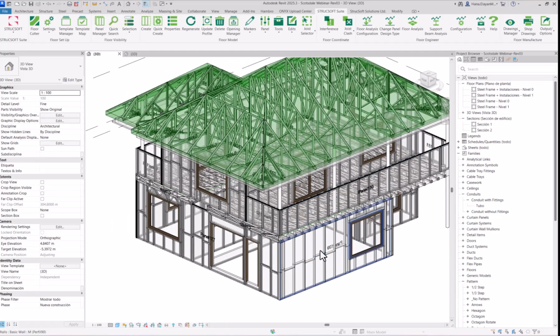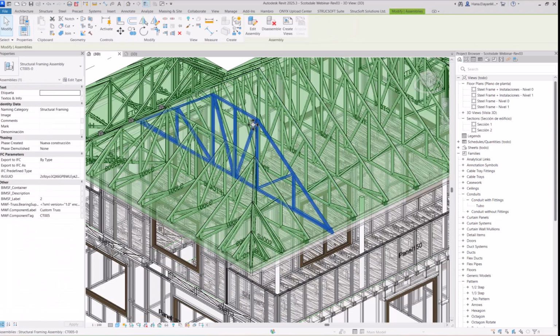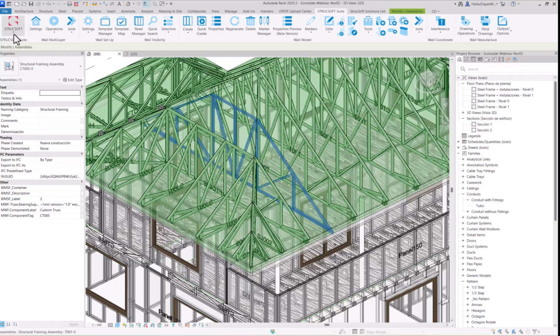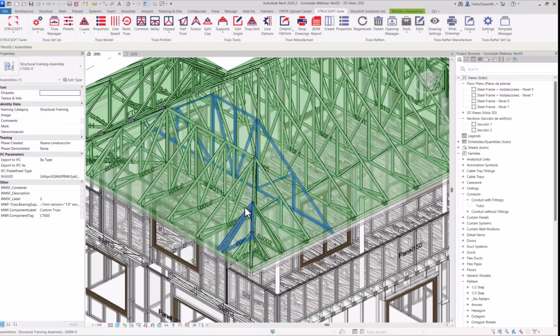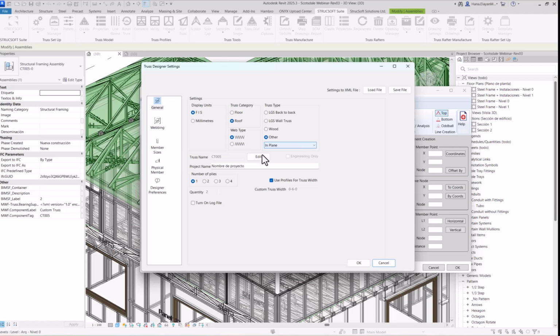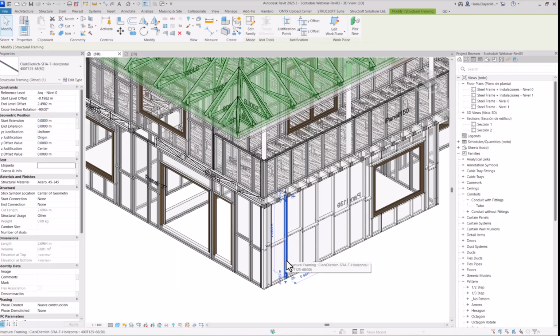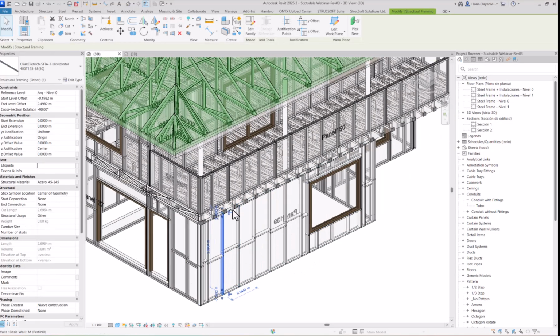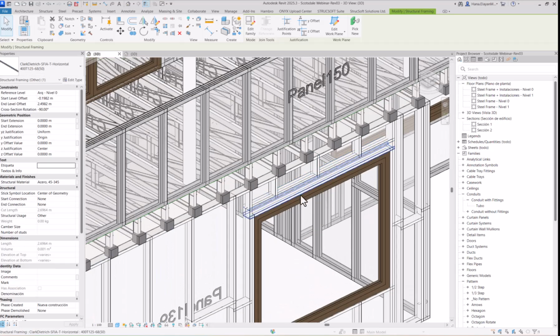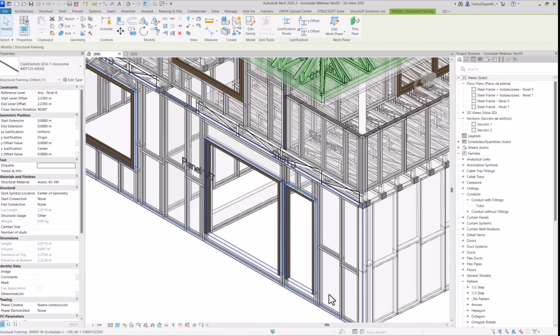Roof trusses follow the same process. In the truss module, pick your truss members. Again, we're using Scottsdale hat trusses here. Saving templates for consistency. Once your panels are set, save your templates. This way, you can reuse them all across your projects, keeping standards consistent and dramatically speeding up your workflow.